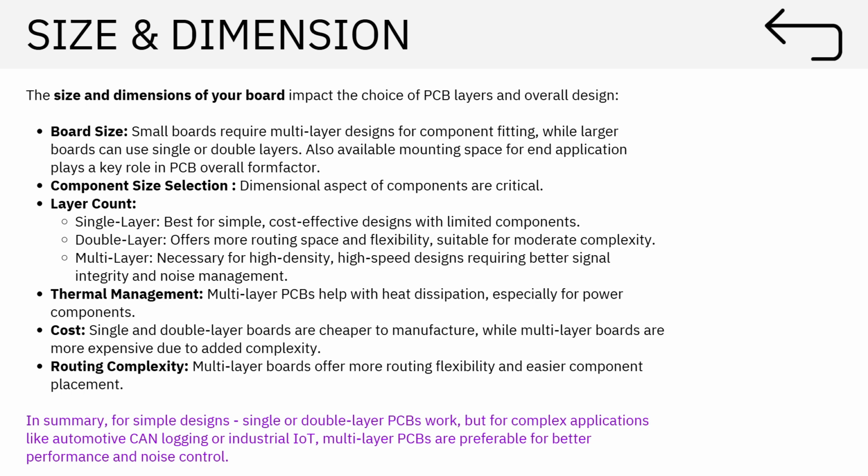Based on the application, you have to see what is the optimum MCU that you have to go for. Then as I talked, in case of layer count, it depends: single layer, double layer, multi-layer. Then you have thermal management. When you design a PCB, based on the size, if you have enough room, you can route things properly and have proper thermal reliefs done. So it derives a lot of things.